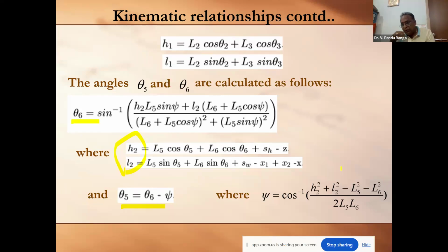Here, for simplicity in computational complexity, we assumed flat footing, which has certain drawbacks, but the reduced computational complexity made us prefer no variation for the swing foot. Then we are left with only one trunk variation, that is, the theta 4 variation.